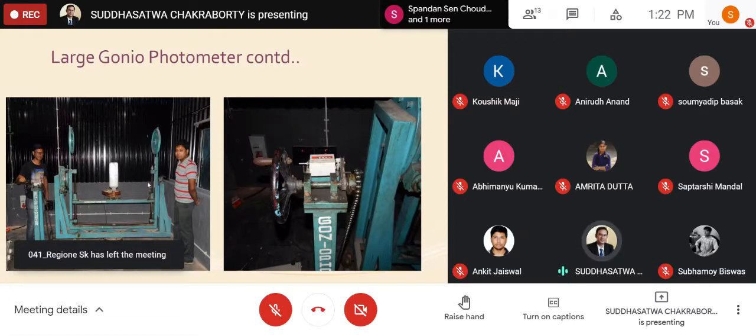So this should preferably be large enough, in such a way that my extended source, this luminaire, will be treated as a point source. That is why my sensor should be placed far away from the source. That is a very, very important criterion you should follow. And now I will be fixing the sensor.